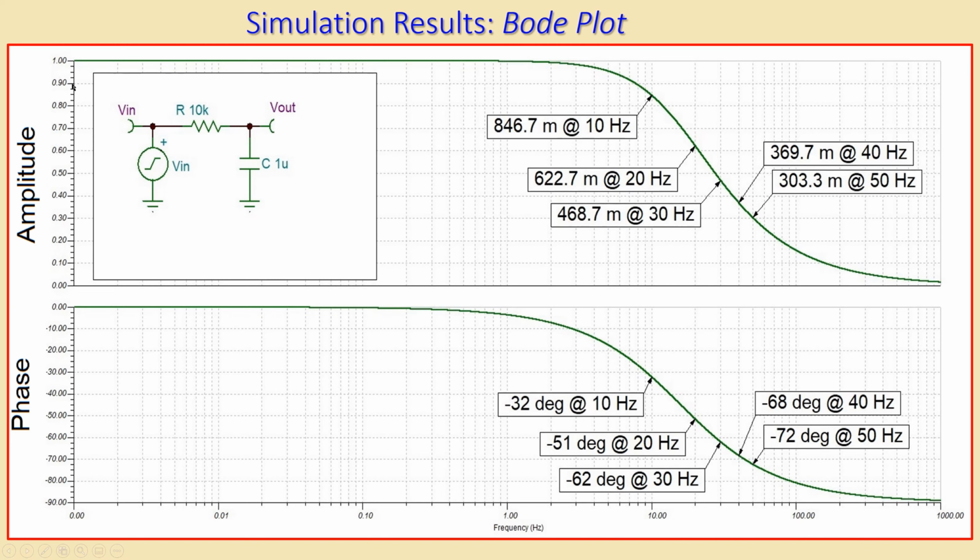So we have plotted here the Bode plot, which is given here with the frequency in log scale. This is 10 millihertz, 100 millihertz, 1 hertz, etc. Of course in log scale. And you will see the magnitude given in amplitude, so just scalar, not in dBs. This is the phase given in degrees. So you'll see it starts at 1, and then it decreases.